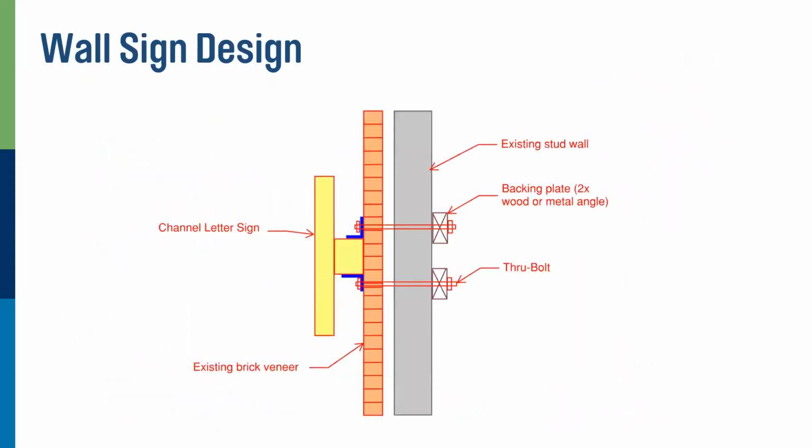So what are we talking about here? This is probably the most common that we see. Normal wall construction is just like this. The yellow here is your channel letter. You have your letters, then you have your raceway behind it. You provide some sort of clip angles coming off of it, and then it's leaned up against the brick. And that's usually where your detail stops.